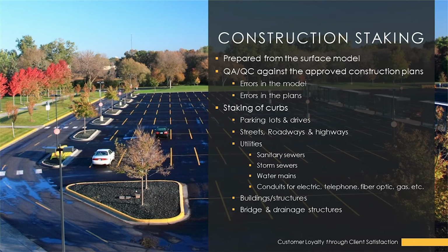If you're staking a roadway, for example, and setting their string line for their automatic curb machine and things of that nature. The other thing is that, typically with staking, very few stakes are needed. Final stakeout of your settlement basins when they're converted to your final SCMs, or the final ponds.